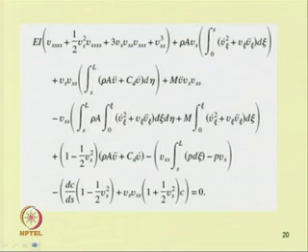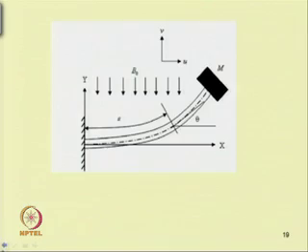In this case the equation of motion will be of this type, in which one can observe that there are two terms, one containing this P term. P is due to the axial loading due to the magnetic field, and one can find another term, C, which is the couple due to this magnetic field. So, one can have a force and a couple. Including the inertia forces acting at an element, one can derive the equation of motion in a similar way.